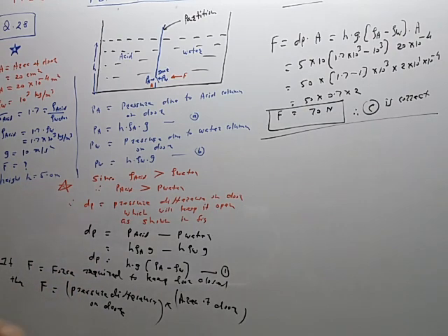So there are two different liquids having different density on the two sides. On one side this is acid having higher density than water. Therefore this pressure PA is more on the door than the pressure of the water column. So this excess pressure is in this direction, and the door will open from left to right, from acid to water in our figure.